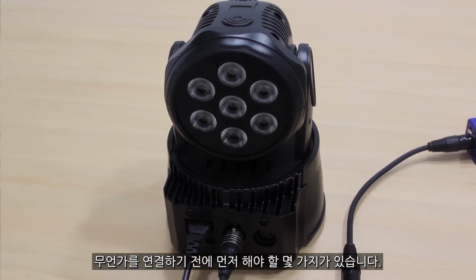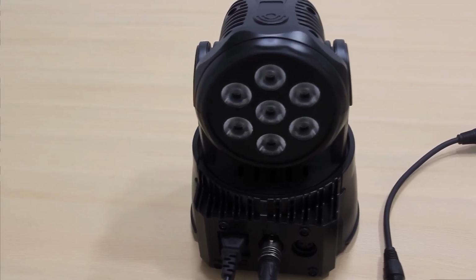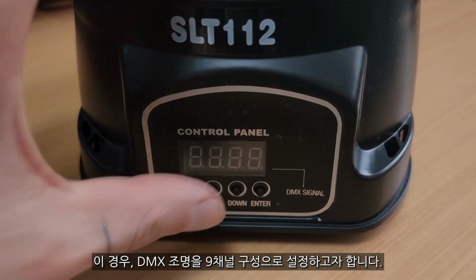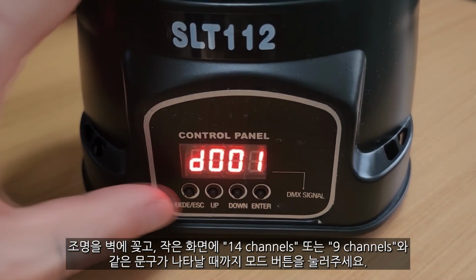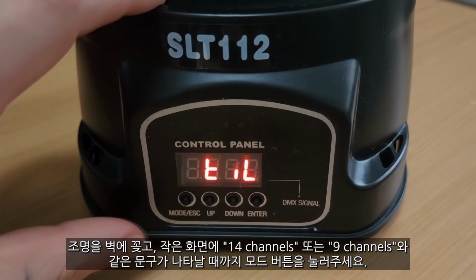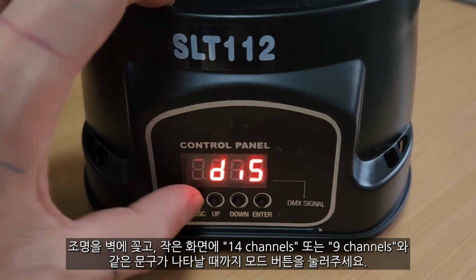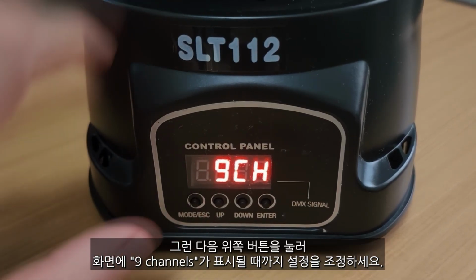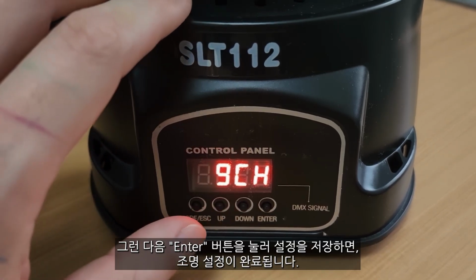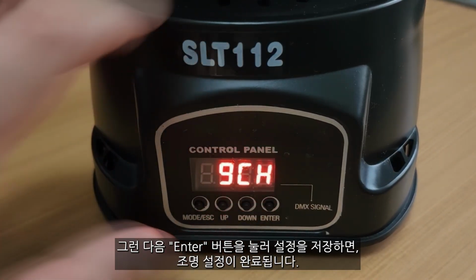Before you connect anything, there are a couple of things you should do. In this case, we want the DMX light to be on a 9-channel configuration. Plug the light into the wall and press the mode button until you see the small screen read something like 14 channels or 9 channels, and then press the up button until that too reads 9 channels. Then press enter. You're good to go on the light.